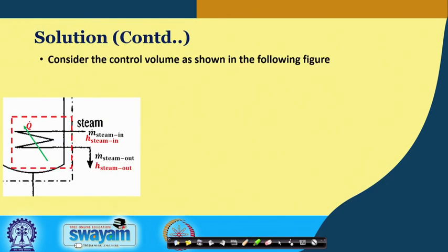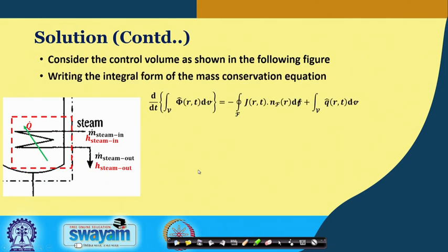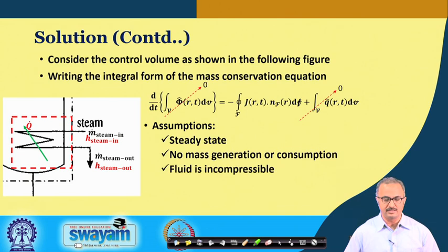Next, we try to find out how this particular heat duty of the steam can be evaluated. For this, we choose another control volume across this pipeline. Here again we see the integral energy balance.